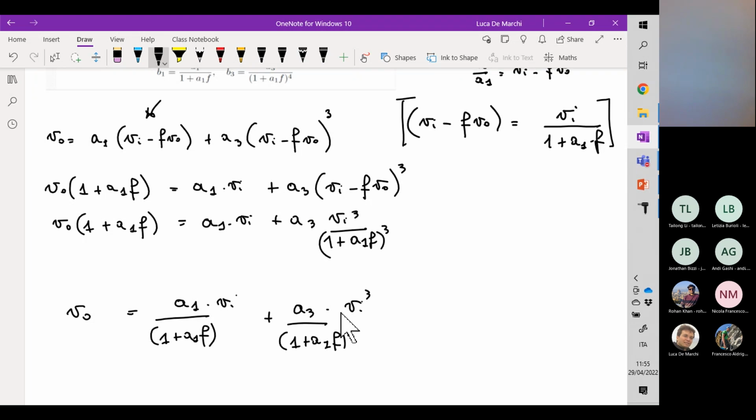Okay, so the effect is something like this. After P1, we have a degradation of the initial DC value of the amplification, and this degradation goes as minus 20 dB per decade. And so after P1, indeed, we do have this degradation.